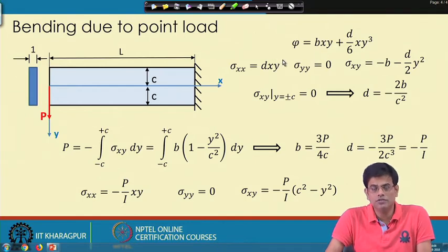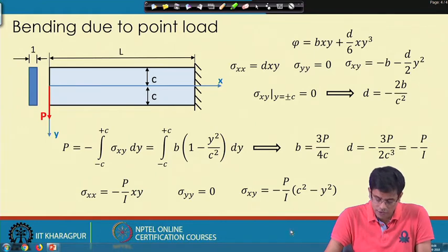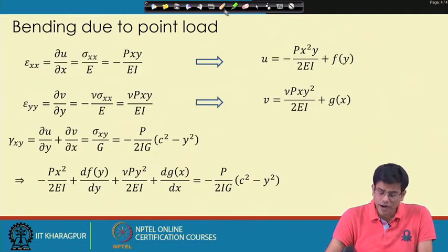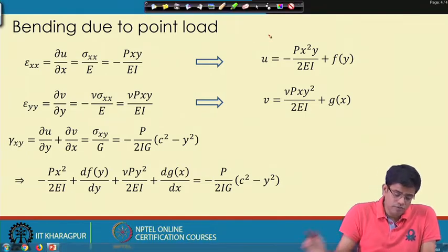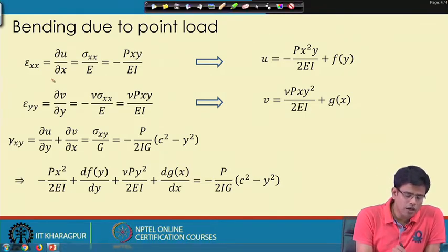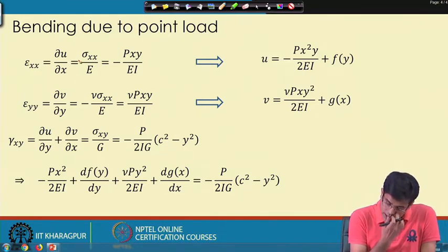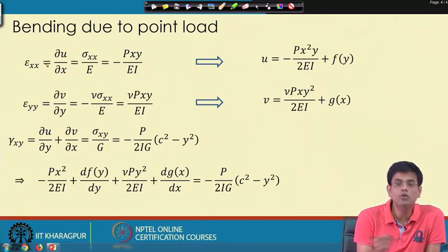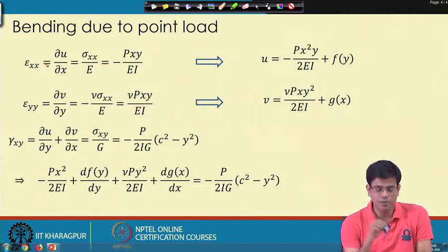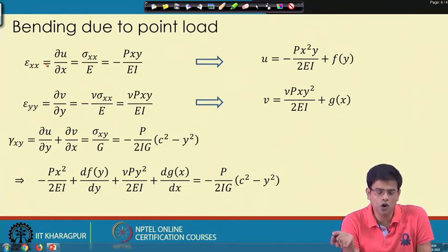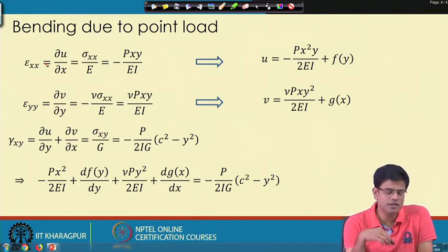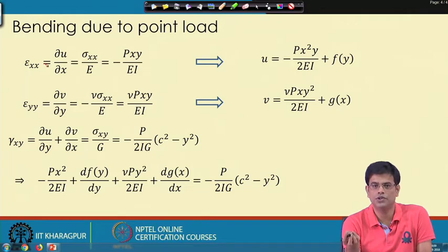Now, our objective here is to find out the displacements. What will be the displacements if we have these stresses? Finding out displacements is very easy, because you know the stresses very well, and if you know the stresses, then you have to invoke the material behavior, which here is the isotropic Hooke's law, isotropic material we are considering, which contains only Poisson's ratio and Young's modulus.